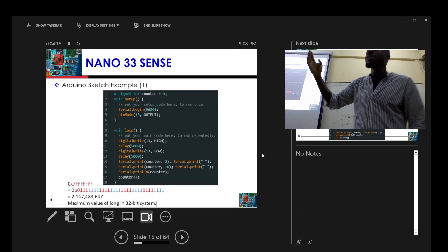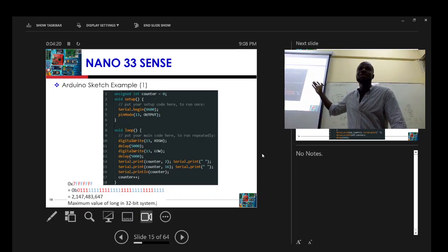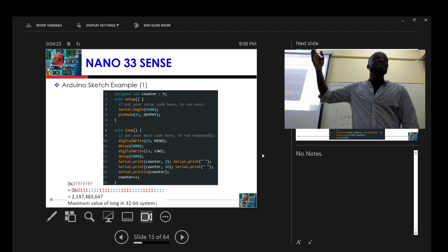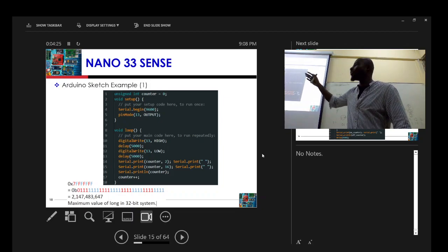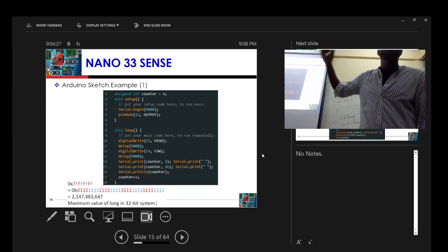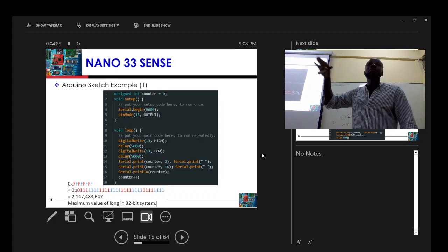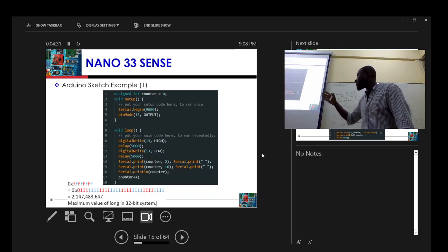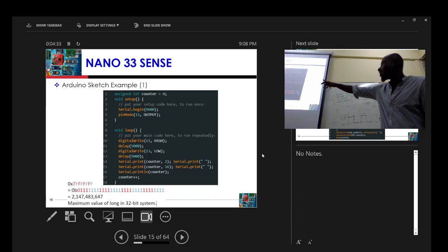Right? After that, I do digital write 13 low. What does that mean? Then I do the delay again, 5,000 again. So it means that I turn it off for how long? 5 seconds.